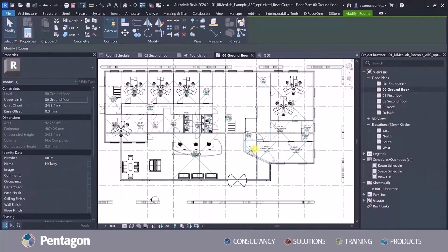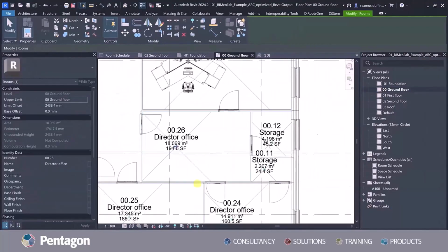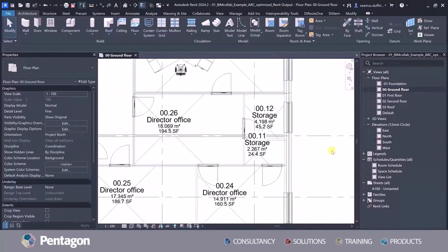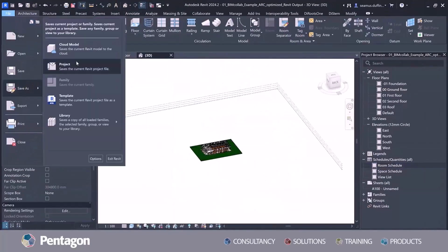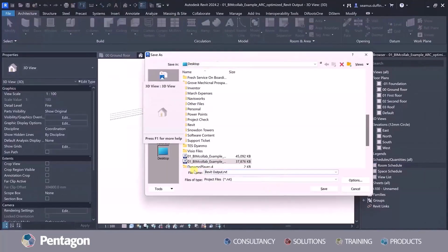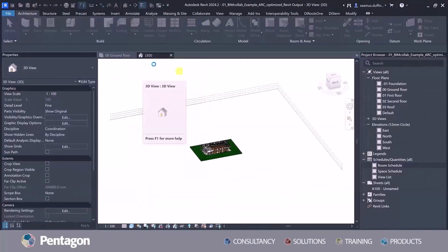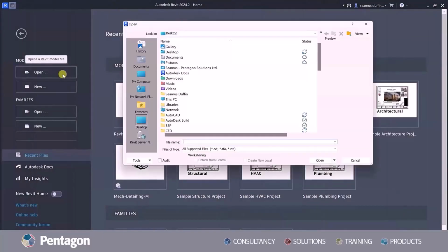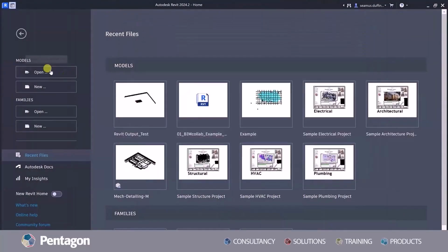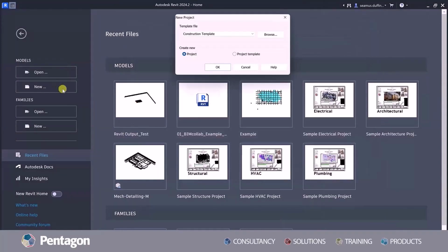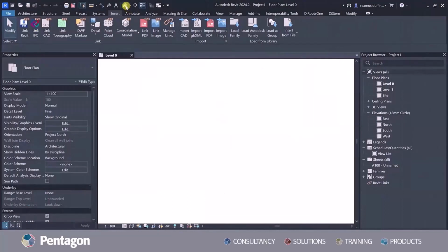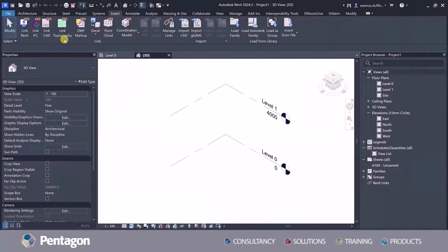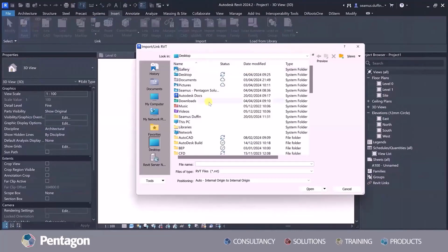In this case, I used a different process where I was able to carry across all my spatial information from AutoCAD, which I can now use within my Revit project. As you can see, the information about my rooms and numbers has been updated accordingly. This is great, as now I can start to use it either at the point in the project where my project's already existing, or I'm starting my project off fresh. This lets me now start to load it in and then start to use that information for, again, the likes of COBie information.